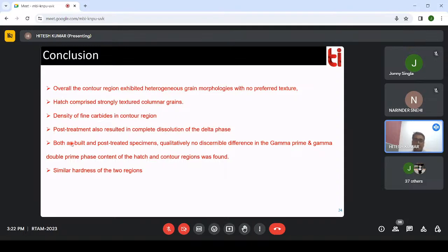But in the H direction, the grain structure is uniform. Meaning, there is a bigger sample with a high number of grains throughout your material, and other than that, those grains are strongly textured. Those grains are aligned in one particular orientation, that is 100. So we can say the H material is more of a textured material.